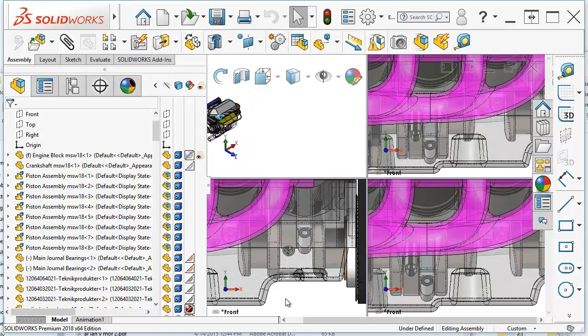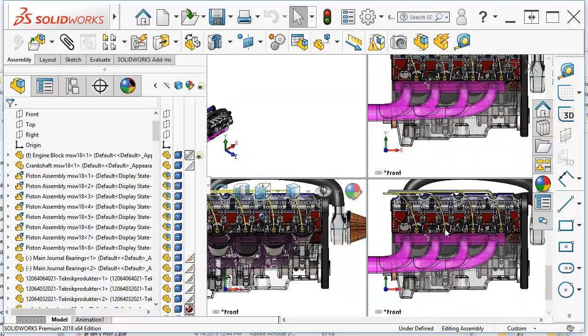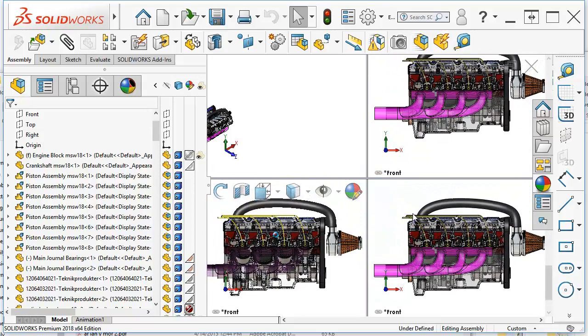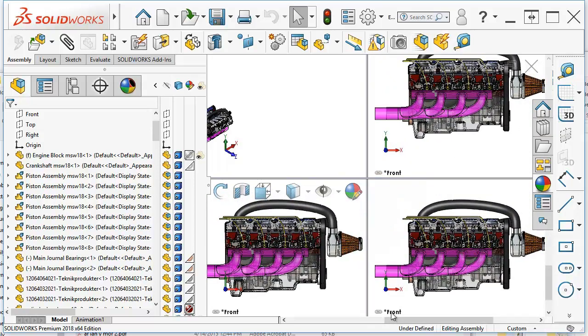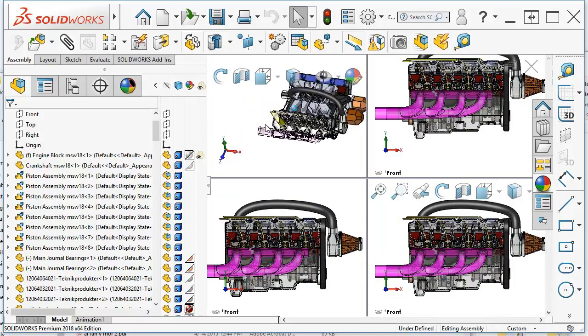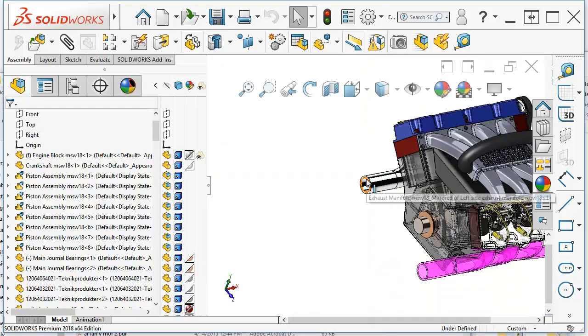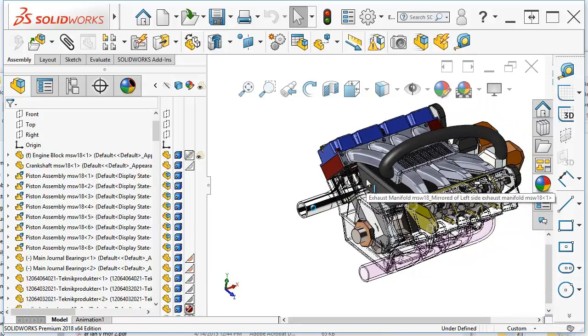You can have these views linked, as these 3 views are linked, but it doesn't allow you to rotate them if you have it set up that way. Be able to rotate the view that's not linked. To set this back, you put the cursor right at the middle and double click. Goes back where it came from.